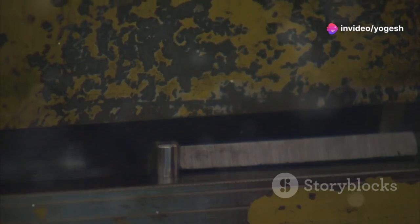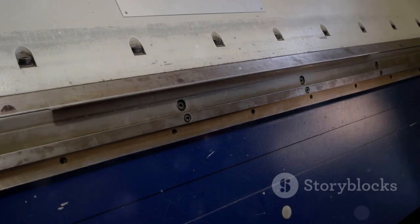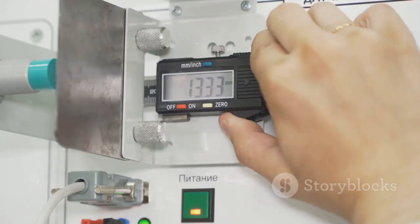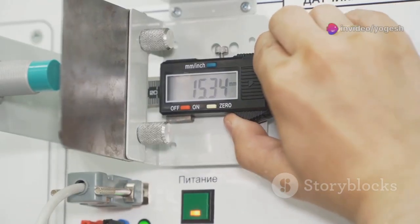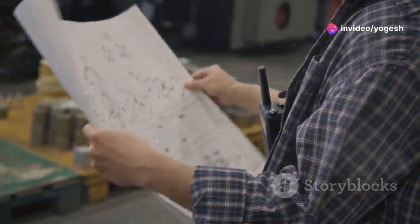Next, let's talk about the K-factor and bend allowance. When you bend metal, it stretches, so the flat pattern isn't just the sum of straight lengths. The K-factor represents where the neutral axis sits in the thickness. It's key for accurate flat patterns. Most CAD software defaults to a K-factor around 0.44, but check with your fabricator for precision.